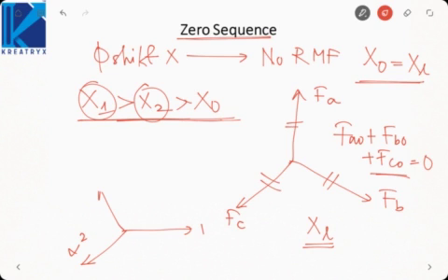Positive sequence reactance is equal to the direct axis reactance because the fault power factor is 0 lagging. Armature current always lies along the d-axis and there is no relative motion, so it encounters the d-axis reactance. In case of negative sequence, the MMF rotates at 2 times ns with respect to the field, so it encounters the d-axis and q-axis alternately, and hence we take the average of the two. In case of zero sequence, no rotating magnetic field is formed and net flux is 0, so there is no armature reaction, and only the leakage component is considered.